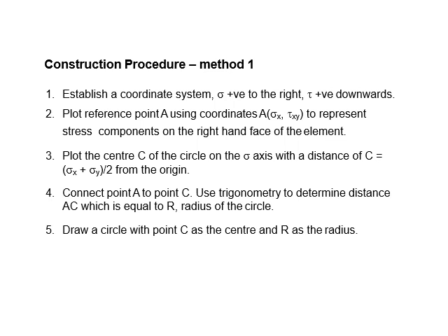So there are two ways of doing Mohr circle. One is to use a graph paper. The other one is just to sketch on a plain paper. If you draw using a graph paper, you use accurate axes, accurate lines. So you have to use drawing tools to aid you, and also you use the scales for the x and y axis, or the normal stress and the shear stress axis. You use the same scale for both axes.